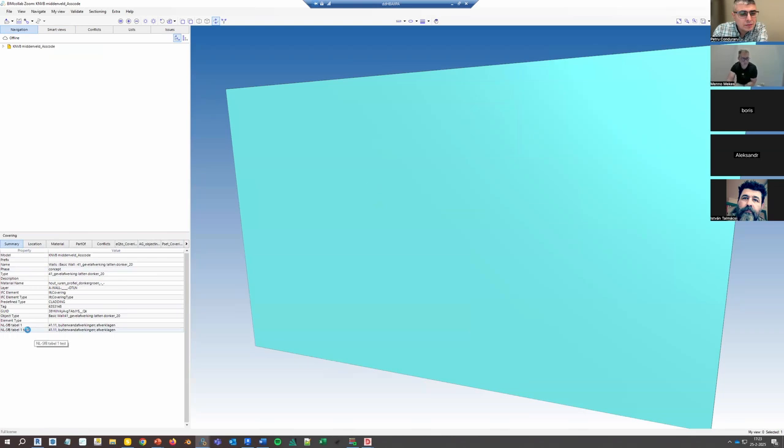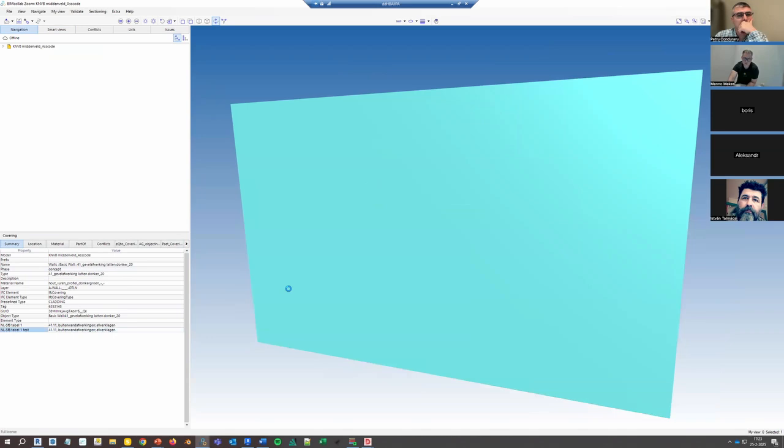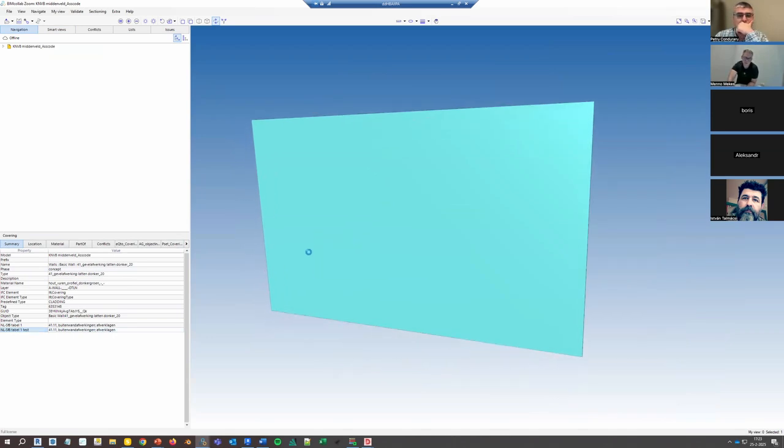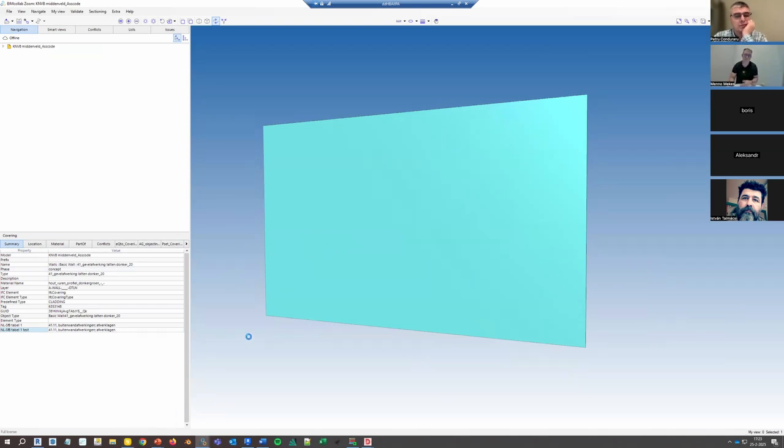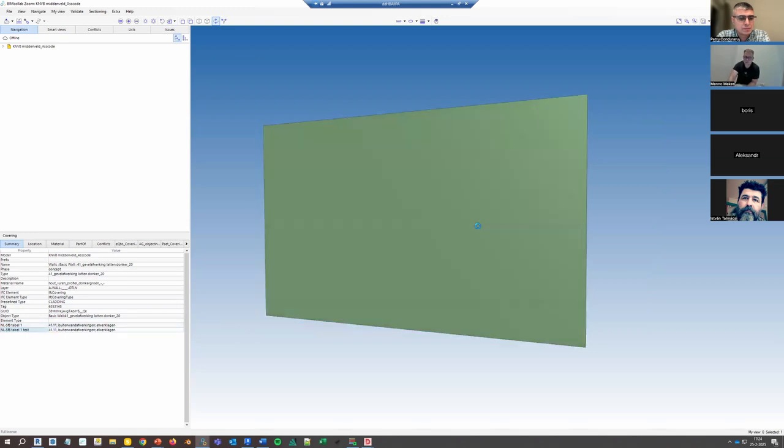Yeah, so here you can see that you can also map your assembly code to a correct classification system if you want. Well, you need it because Uniformat is not used in our country, so Uniformat is never correct. But the common practice is that people who receive these models, the BIM coordinators and the contractors, create monster classifications so they can just grab everything and then fix it with one big classification or one rule set or whatever. So they will have the correct information because usually the code like 4111 is usually correct.